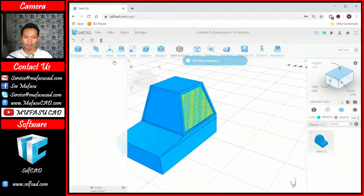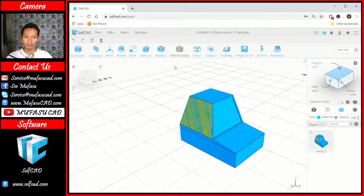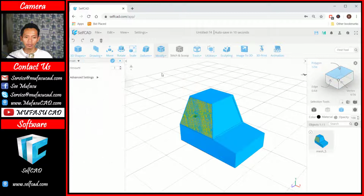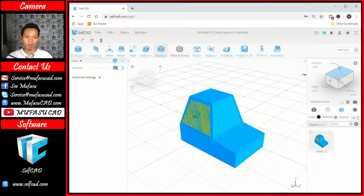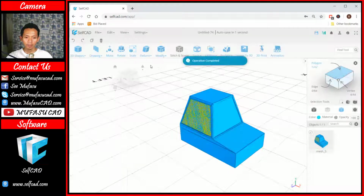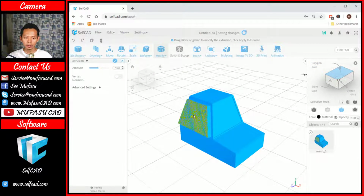Click OK. Now we create again in this face. Use the insert tool and then set amount 2. The next, insert again with amount 1. Now we can use extrusion to extrude this face.